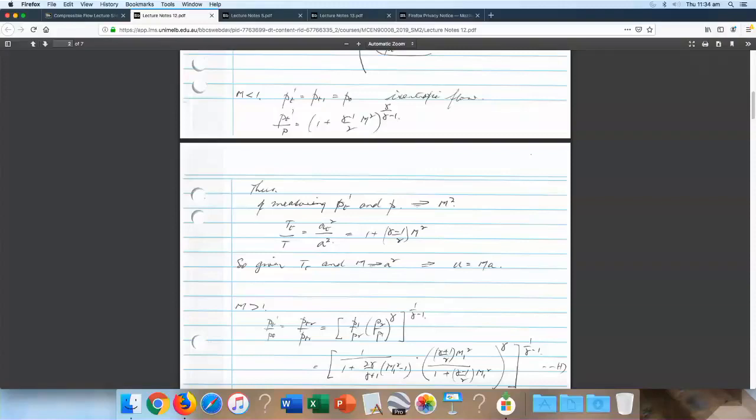If the pressure outside is higher than the pressure at the exit, then I could easily have either an oblique shock or a normal shock at the exit, or that normal shock at the exit could migrate upstream.